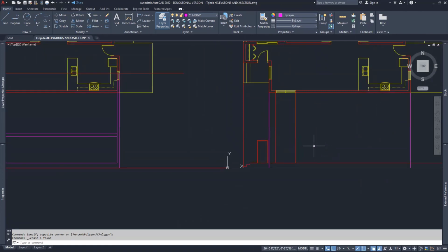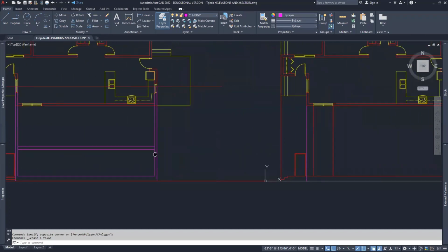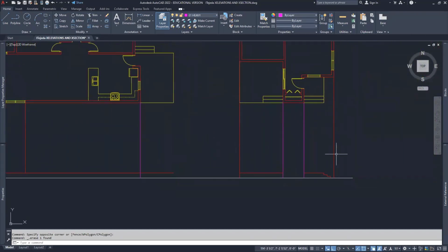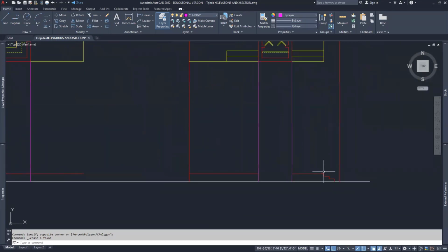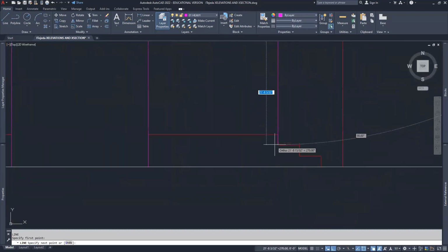Now it's a matter of addressing the steps on the front elevation, or rather, sorry, wrong direction. Here we go, on the front elevation. So the reality is this. It's just a matter of drawing a line. So I'll type L, enter, from this point straight down. And it looks like it's already going to coincide with the line that's there. So I probably don't need this line. I'll just tap the escape key and I'll remind myself that this is where the steps end.